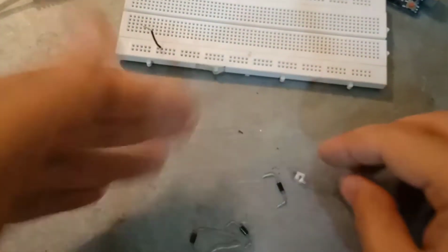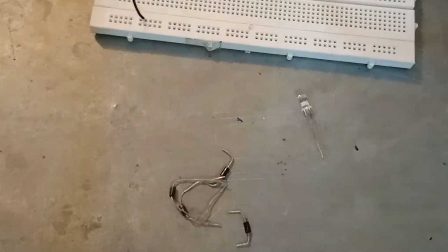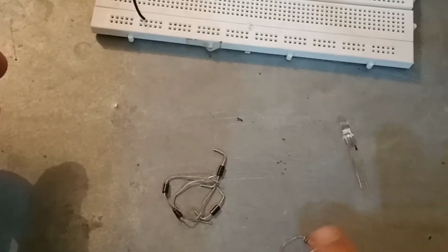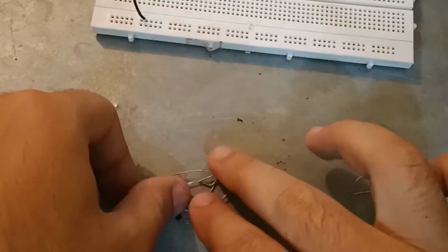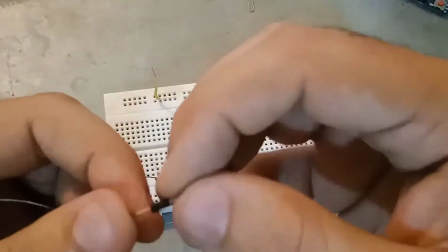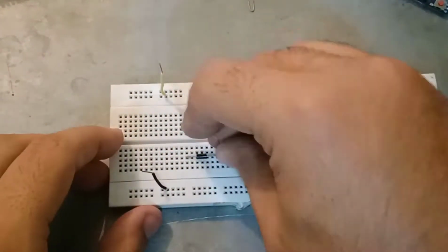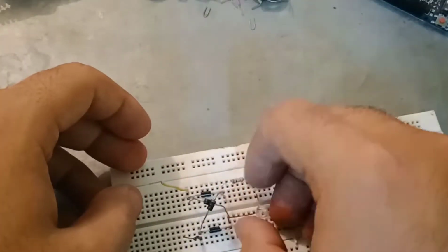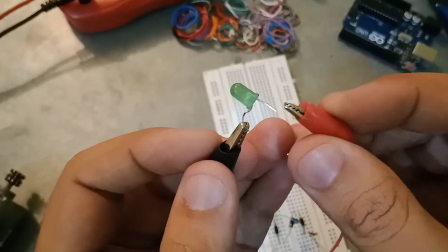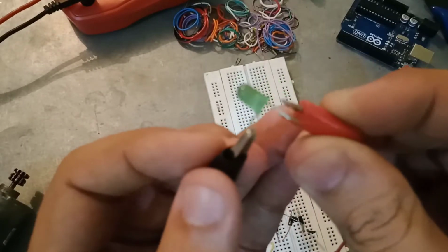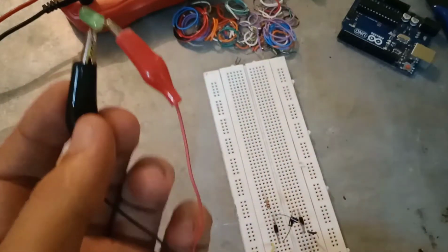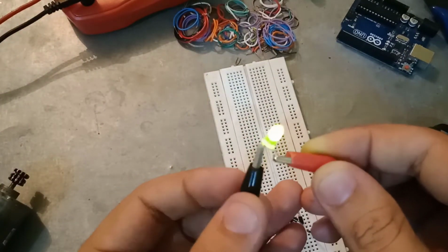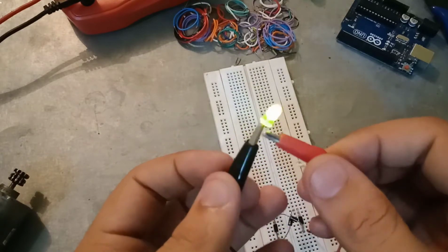So these are all the components that we're going to need for this circuit. So one LED, because LED always lights up in the forward bias, a current limiting resistor, and 4 diodes. So I'm going to quickly build the circuit on the breadboard, and then we are going to see if the circuit works according to the schematic diagram. So I'm going to first plug it in the opposite polarity and let's see if it lights up. So it doesn't light up. I'm going to wire it up in the correct polarity, and as you can see, the LED lights up.